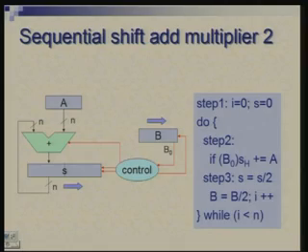So, here is the modified circuit, where what we are trying to do basically is that we are adding A to the left half of S. SH is denoting the high end of S, or the upper half of S. So, A is always added in that position, and we are making sure that the two are correctly aligned.